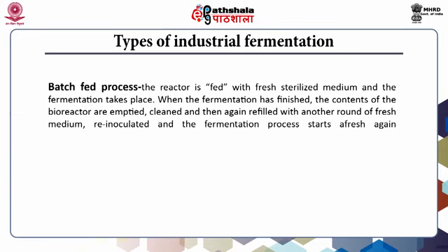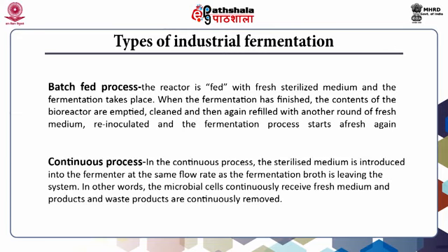What is the continuous process? In the continuous process, the sterilized medium is introduced into the fermenter at the same flow rate as the fermentation broth is leaving the system. This leads to achievement of a steady state production. In other words, the microbial cells continuously receive fresh medium, and product and byproduct are continuously removed.